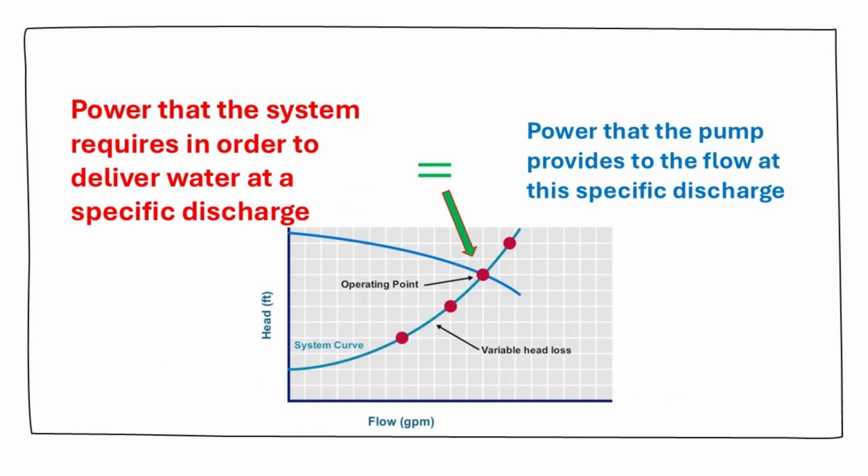The pump curve and system curve are combined to create the pump system curve or total head curve, which shows the total head that the pump must overcome to deliver a specific flow rate through the system. The intersection of the pump curve and the system curve represents the pump's operating point, where the flow rate and head produced by the pump match the pressure or head required by the system. This assumes the pump is in a like-new condition, has no air entrainment, and is not suction cavitating. Essentially, the operating point is the point where the pump can effectively balance the demands of the system it's working against, and is crucial for selecting the right pump for a specific application.